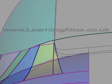So you have the initial curve on surface there, you've detached it there, you've aligned a degree 5 curve to here, which you've direct modeled at the end, and then you've run a curve from there to y equals 0. You've found curvature here, you've shaped this curve in both views, and now you are ready to project this curve onto the C-pillar, and that gives you, if you like, the trim edge that you need to build these patches.